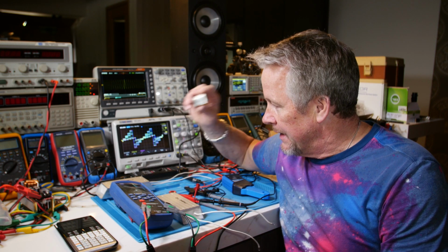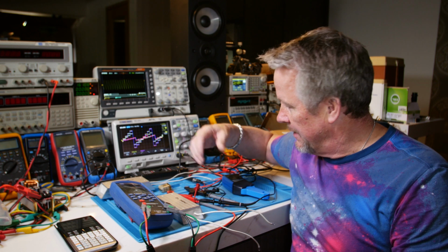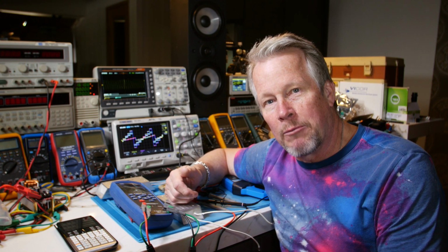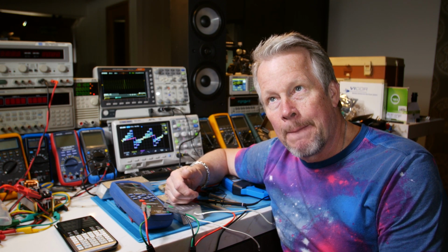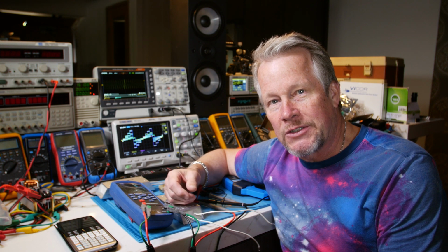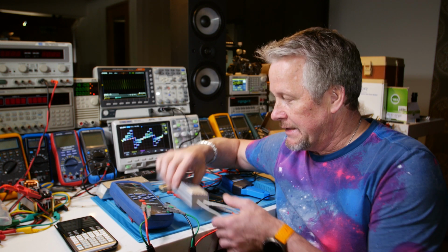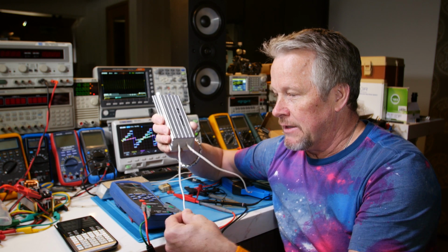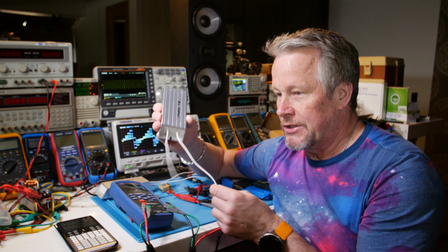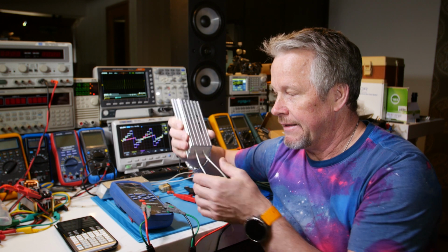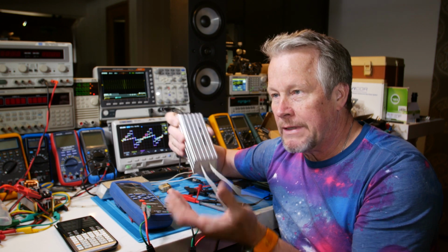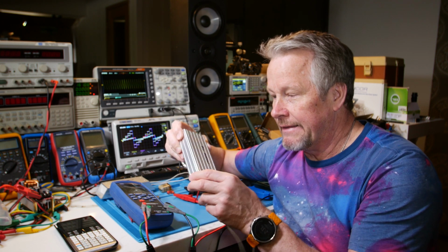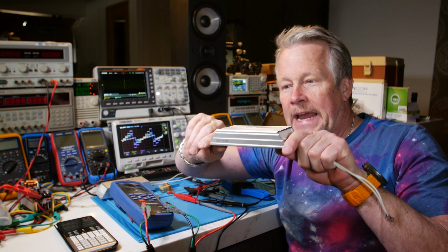And a capacitor, an inductor, resistor, they all have what we call parasitics. They're the imperfections, if you want. You know, for instance, resistor, right? Non-inductive, but then you have these long leads, so they're going to create some inductance. Just the fact that you have some lead length. A through-hole part, even a surface mount part, they have lead length. So imagine this is a gigantic surface mount.